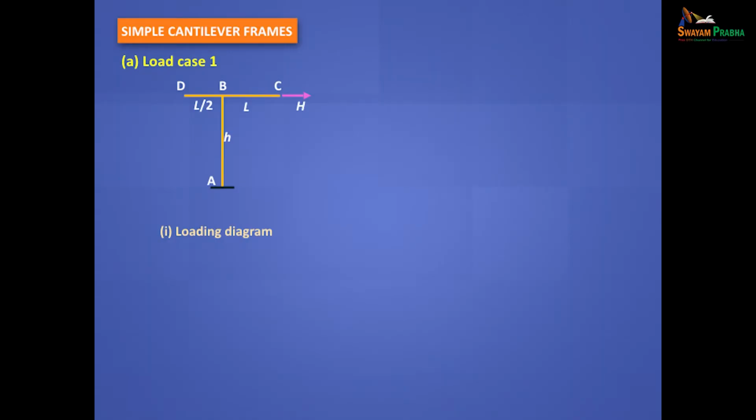Look at this. You are having tension on top. So it will be like that. You have tension on the inner side. Are you getting it? More or less a shape like this. And this B may not move much, but C is going to move a lot. All right. Good. We'll go, and you can draw your shear force and axial force diagram.